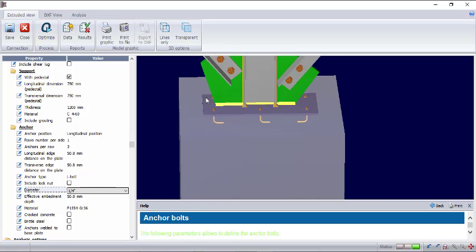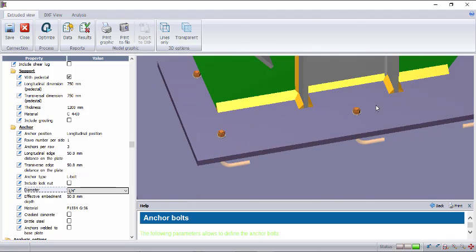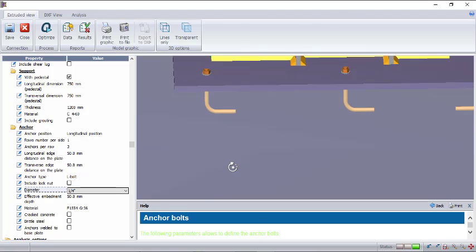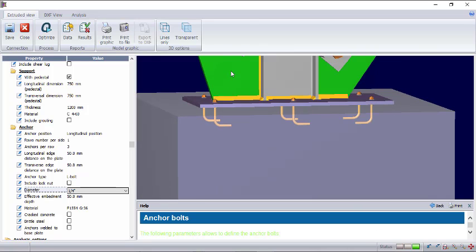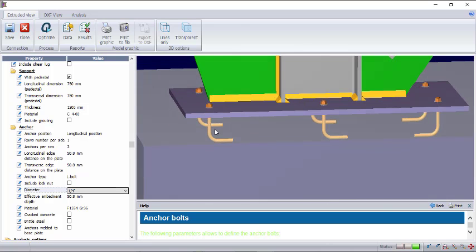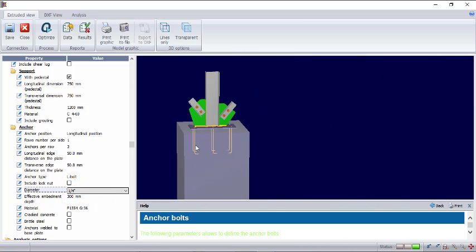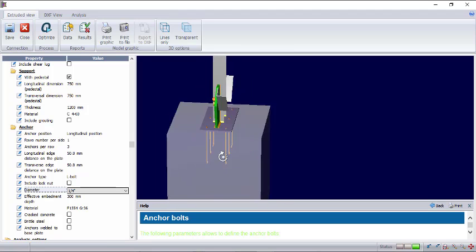So you realize that after I clicked on the optimize, the number of bolts I put is still there. However, this length, you can see the length can work. This short length, as short as it is, it will work, but I think structurally it is not making sense, so I have to increase it. So let me increase the effective depth again. I will change that to, let's say 300 mm. Okay, so that is now long. That's long enough.